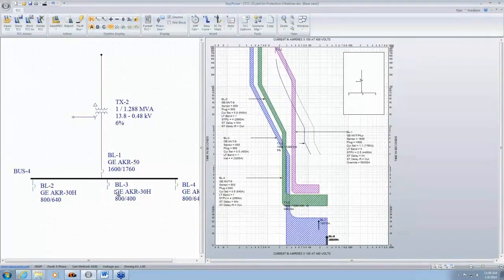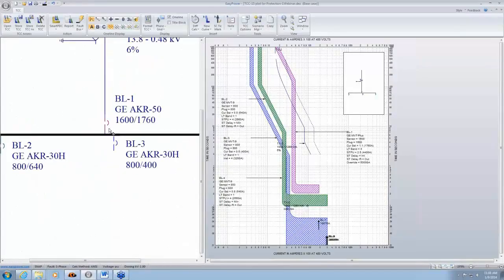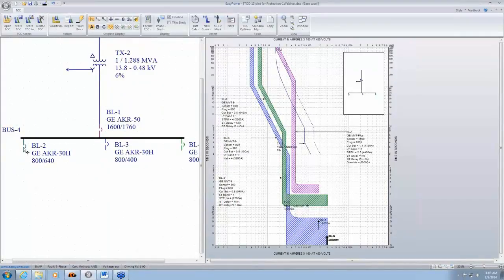Now the question is, I've got feeder breakers here crisscrossing. The curves are crisscrossing. Question is, do I need to fix that? Since they're on the same level, you do not need to coordinate feeder breakers with each other. You only do between different levels. So I would say main is one level, all these circuit breakers are second level. So you have to look only between upstream and downstream circuit breakers or fuses. So these can be left as it is, it's fine.